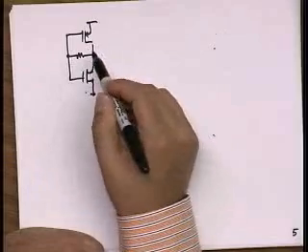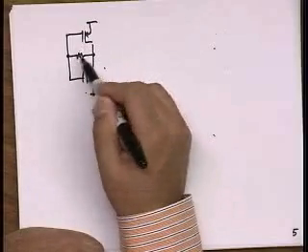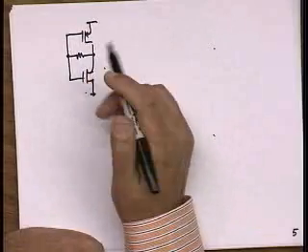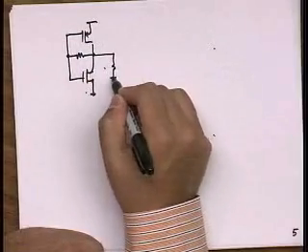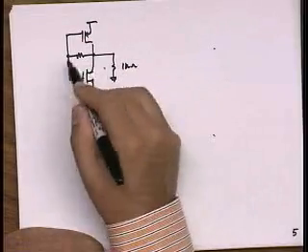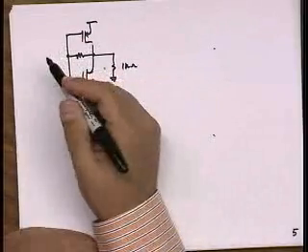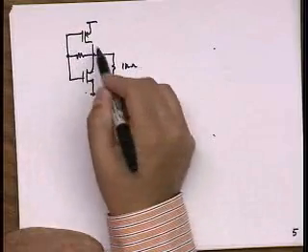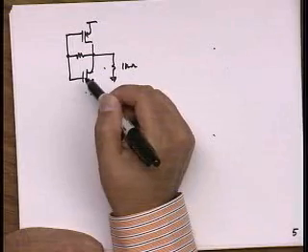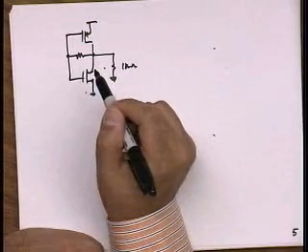And in fact, if you don't like this resistor's influence on your circuit, you just make it a large resistor, right? So let's say I'm driving a kilo ohm, and I make this, let's say 10K, 50K. Then effectively it's just a DC. It's only going to affect the DC operation of the circuit. It will not affect the AC operation.